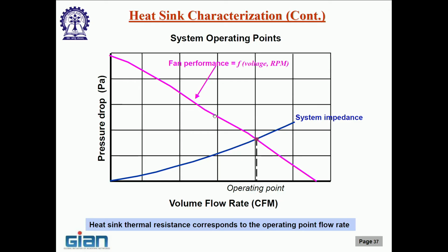On our discussion on thermal technologies, cooling technologies. So, just before the break we talked about how do you characterize a heat sink, and we saw that of course thermal resistance is the single most important parameter, because that is what we want to minimize in order to keep the temperatures cool or increase the amount of heat that we can dissipate. But it is also important to know at what flow rate I am going to take that thermal resistance, and that will depend on the geometry of the heat sink that you are using and what fan you are using.